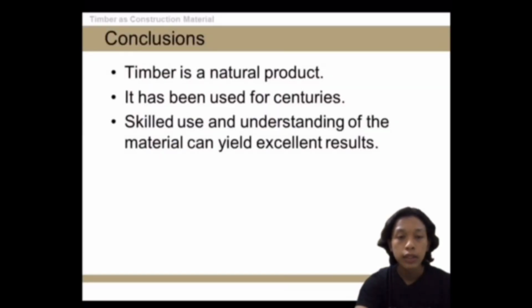The conclusion. The moisture content level is expressed as a percentage of the oven dry weight of the timber. Growing trees will typically be stated as having a moisture content of more than 100%, and even at a moisture content of around 25%, water will be partially filling the structural wood fiber. Entirely, as the timber dries, this moisture is lost, lowering the weight although not affecting the timber dimensionally.